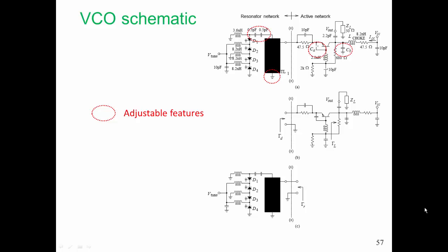We also have those additional 0.5 picofarad capacitors, 2 capacitors in series, of course giving us a 0.25 picofarad capacitor, but we could have needed some other values. Those values of capacitance are used to fine-tune the capacitance values that we can get from the varactor diodes, because in fact there isn't a large variety of capacitance values that we can get. So we can fine-tune the tuning range.